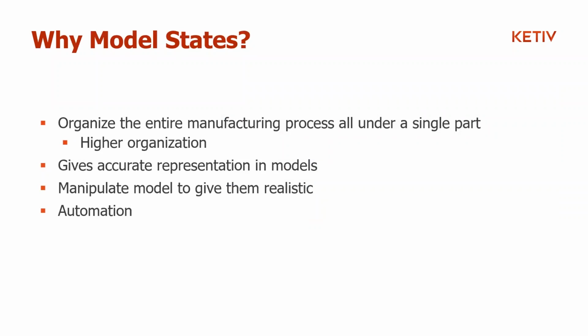So why model states? Why is model states so good? So number one pro thing that I've seen about model states is you can organize different manufacturing processes all under a single part. So for example, if you start with a blank and then down the road it gets punched, you could show that within one part versus showing 4 different parts. And especially if it's all under one part number, your organization becomes much, much greater.